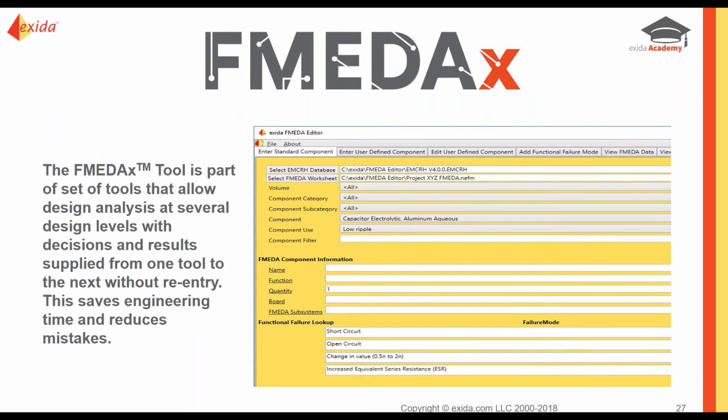And to do this, there's a tool out there. This is one of our newest tools, so I am really excited to show you this in my webinar. It's the FMEDA tool. It can let you do your FMEDA. To do that, you will have your bill of material, you will have your drawings, and you will add part by part and consider how each part will be affected if it breaks, if it binds, if it leaks, if it gets stuck, if it shears, if it bends, and if it will lead to a dangerous situation or a spurious trip situation. At the end, you can then say your diagnostics and evaluate the proof test per the FMEDA. And you can make it easier if you have a FMEDA tool.